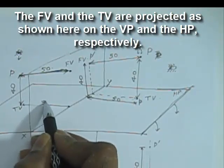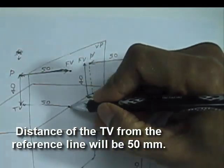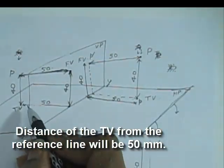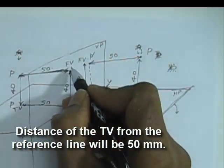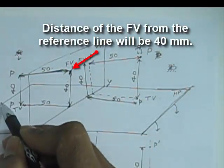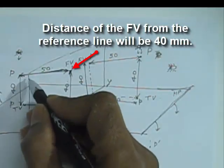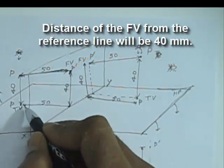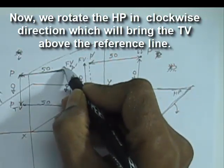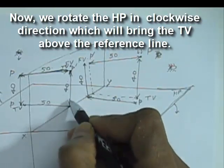The front view is on the VP and the top view is on the HP. So front view is 40 mm away from the reference line and top view is 50 mm away from the reference line. Now the horizontal plane will be rotated in clockwise direction such that the top view and the front view both will fall above the reference line when we are drawing the orthographic projection.